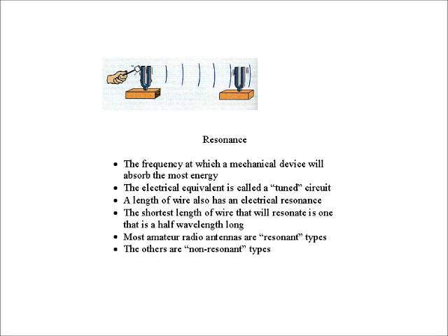It's resonant. And what is resonant in that instance? The same spot on the tire is hitting the ground in exactly the same place as it rotates. That's true, but what's vibrating? It's the entire car body that is absorbing the most amount of energy at that particular rate. Its natural mechanical resonance is the frequency at which that tire is slapping the ground, just as you described.